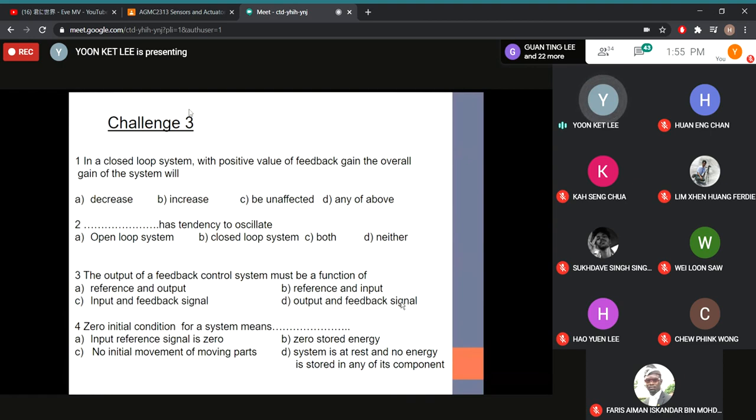Then what is the next step? 10 minus 10.5 is negative 0.5, so it is a negative gain. Then I need to decrease. When I decrease, there will be an undershoot. Maybe it will give you 9.8.